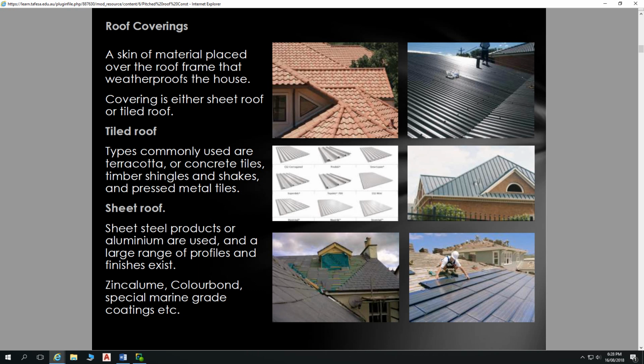And under our roof sheeting, the spacing of our purlins or battens, if they're timbers on flat, is as specified by the sheet manufacturer, but typically spacings are around 900 for end spans and 1200 for internals. So significantly different once again from our tile roofing.